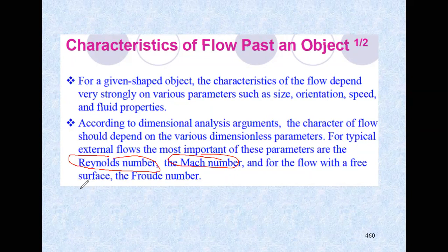Okay, but actually in physical terms, the Reynolds number is the ratio between the inertial force and the viscous force. So there is a viscous effect on it. So there is an inertial force. Density is related to the inertia, the mass that it has, and you have velocity over here, and you have characteristic length.